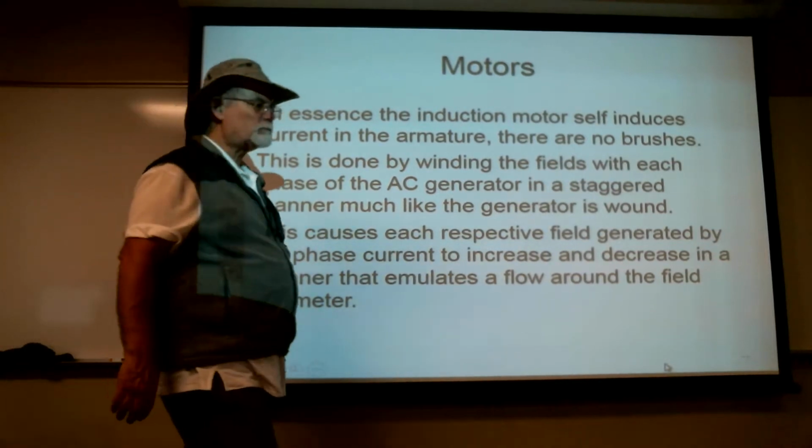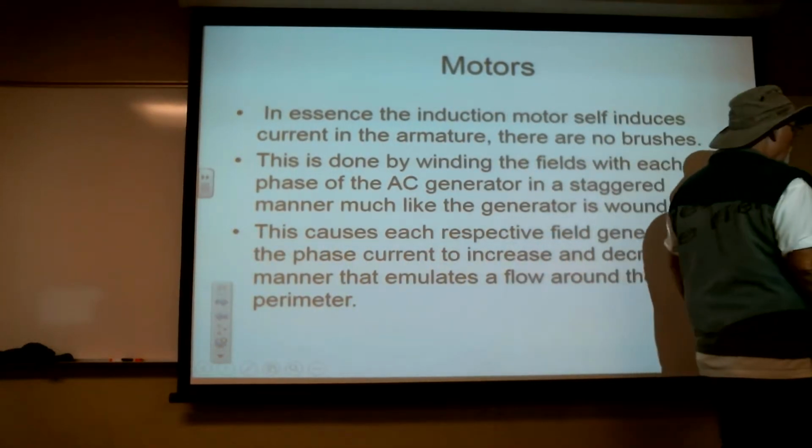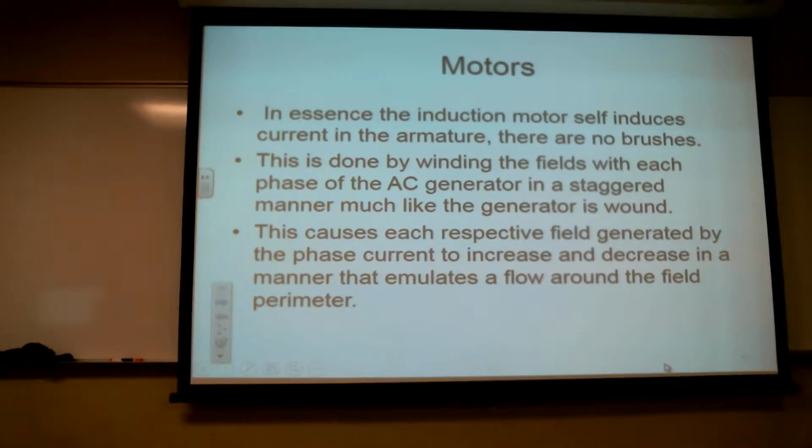So let's talk about the induction motor. If I take a physical magnet and start spinning it around a barrel, and I have a bunch of iron bars all hooked to a little spindle, as I start moving that magnet around, the magnetic fields are going to start cutting those iron bars, right? And as they start cutting those iron bars, aren't they going to induce some current flow in the iron bars? Mm-hmm.